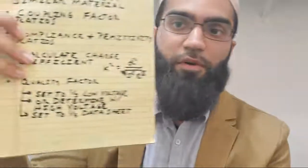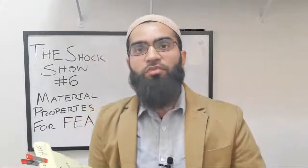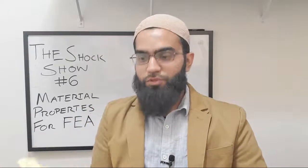The next is if you're just stuck with the datasheet, because sometimes you are, honestly. If you're just stuck with the datasheet, just divide that datasheet value by 5. Divide it by 5. Therefore, you will get something similar to what you'll find in practice at high voltage.